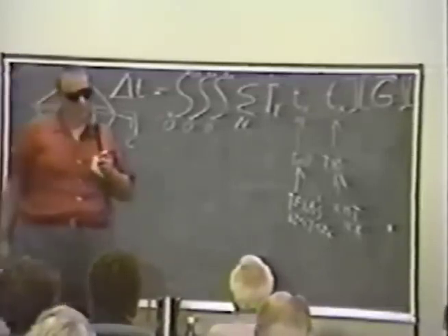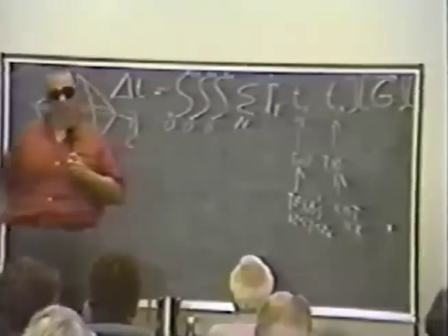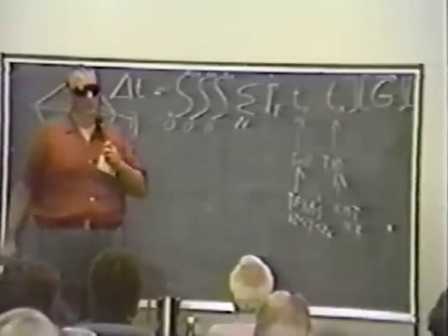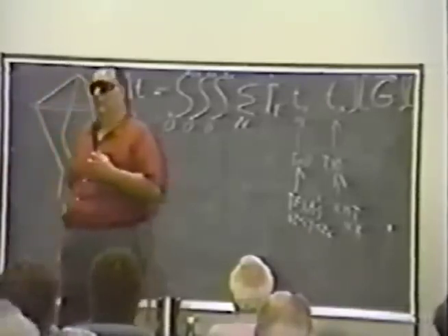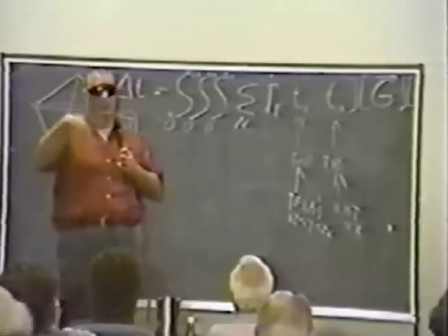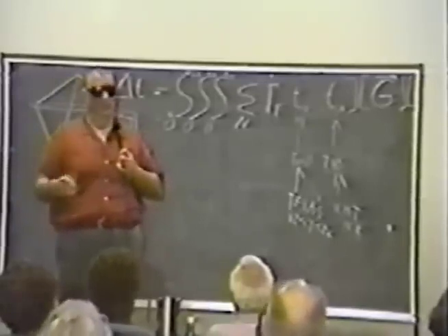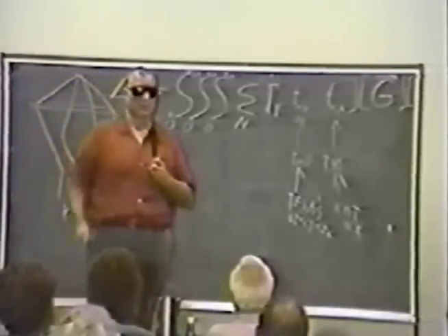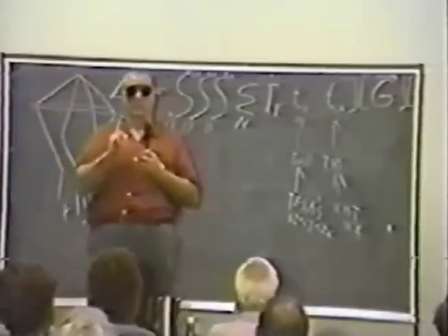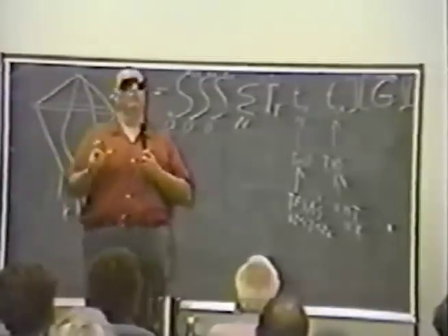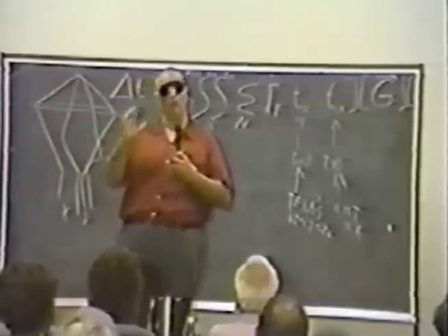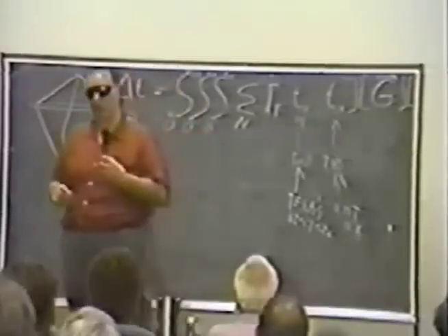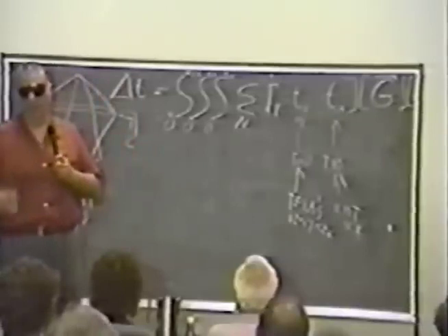I have a number of these devices. Al has one in his possession also. They were built for the FAA in the 50s and 60s. You turn the thing on, you hear it speed up, it whirls its way up, and then you hear it lock in. It doesn't lock into the power line. Why? It's a synchronous motor that they drive it with, 1800 RPM, which is a 4-pole motor on 60 hertz, or 30 hertz rotation.